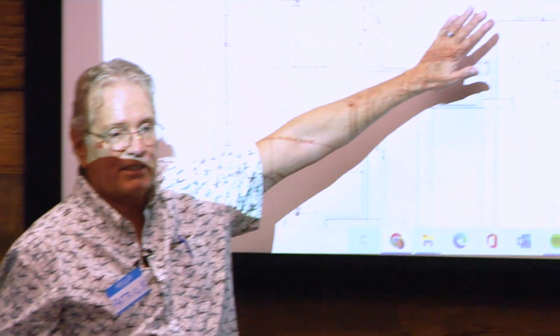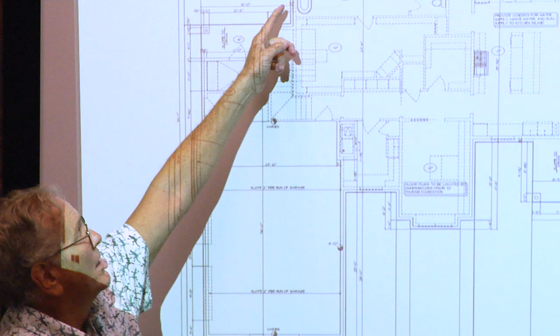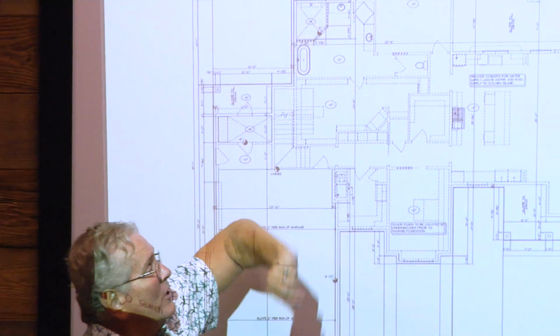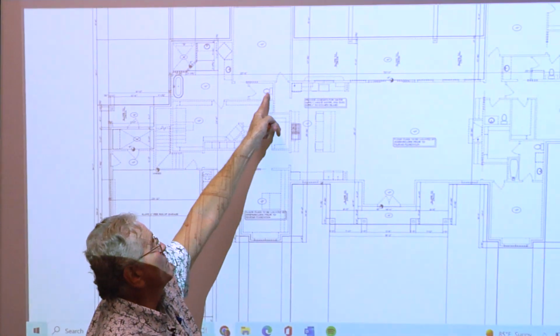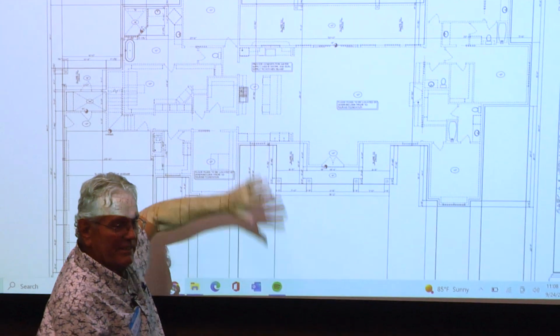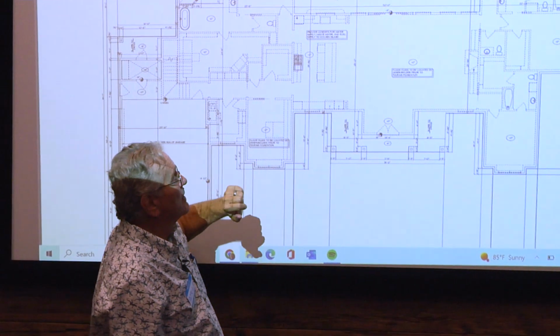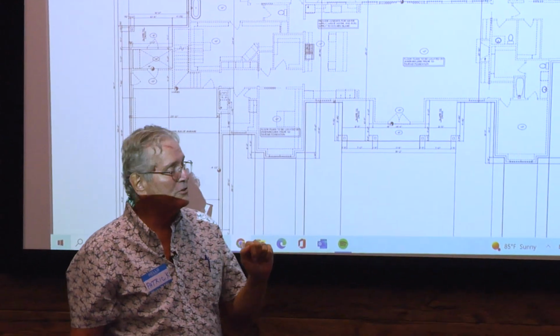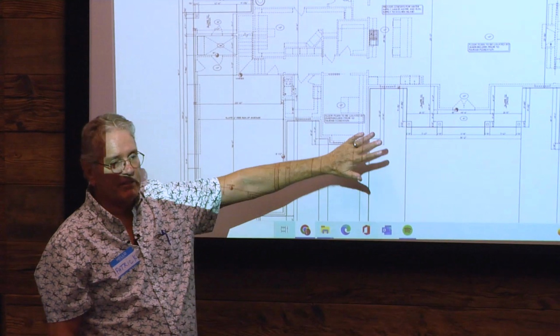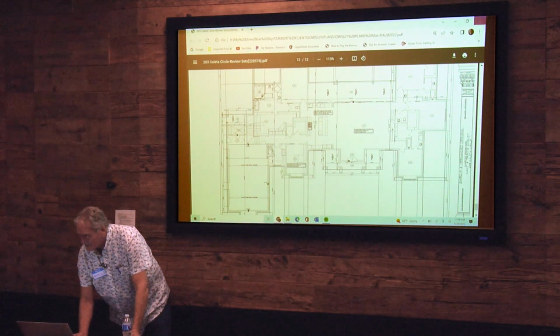But I'll tell you, designers can actually take this foundation plan and put a dimension on where this fixture needs to sit, that drain, where this commode needs to sit, and then the plumber just goes out and lays it out per the fixture drawing. So it's really called a fixture drawing, and it's laid out on the foundation plan.